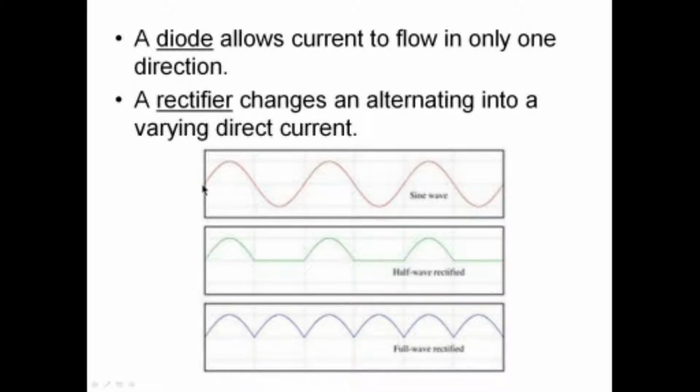So if I'm looking at a power supply here, and I have alternating current coming into my power supply, and it goes to the rectifier. Well, remember, the diode only lets the current flow one direction. So what I end up with, if I have just a simple diode rectifier, is a lump of voltage there, a lump of voltage there, a lump of voltage there. And it's direct current, isn't it, because it's all flowing in the same direction, but it's not very smooth. Okay, so I need my filter in my power supply to smooth that out into smooth direct current.